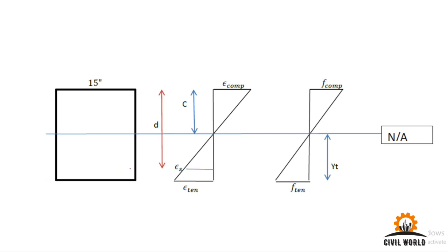This is in the case of a single layer of reinforcement bars. You have to provide 1.5 inches minimum concrete cover, which is clear cover, and then till the centroid of the bar we assume a number 8 bar, so that is 0.5 inches, and we assume a stirrup of number 4 stirrup.